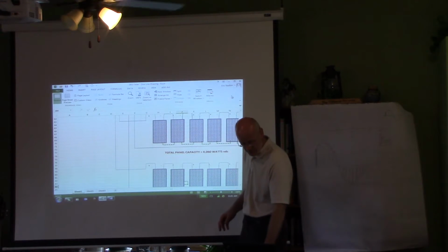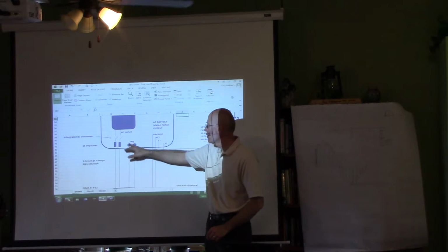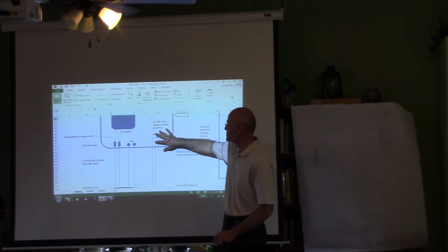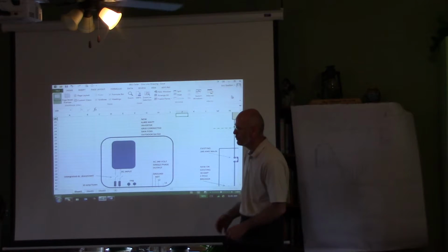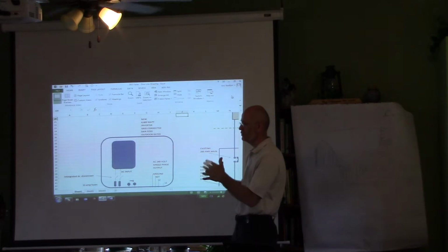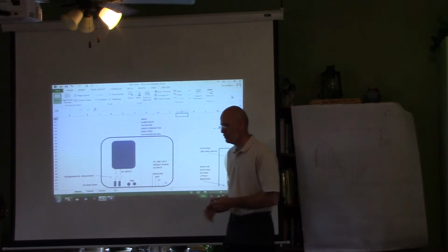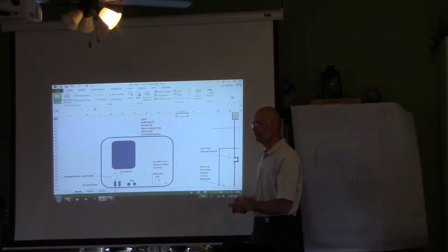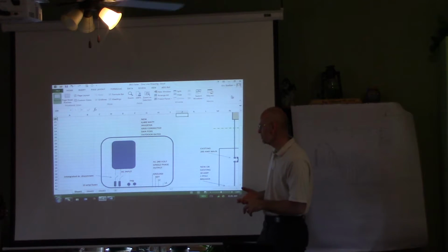Once you hook them to the inverter, is that current gonna flow? Probably not until you hook this up. And it's been there for 5 minutes. This particular inverter is meant for multiple types of systems. It can do 208 3-phase on 2 legs, or it can do 220 and do a grounded neutral or a single phase. So we have to program this inverter. When we get to that in probably about a month, less than a month maybe, it depends on Eric, you guys, when you get your system built. So we have to program this for the right voltage and stuff.